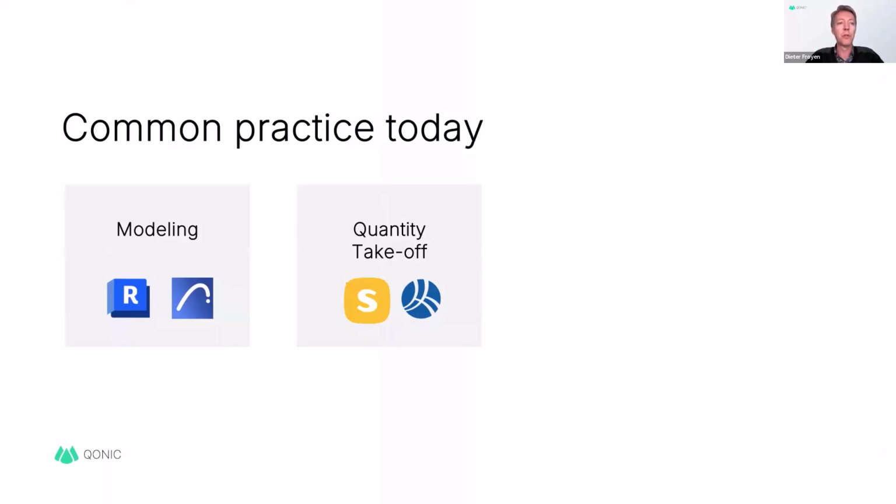It's also possible to export the files as an IFC file containing those base quantities. And on the other hand, you have IFC-based software, and there are many types. You can have viewers, you have software used for coordination, and they almost all let you do a quantity takeoff.